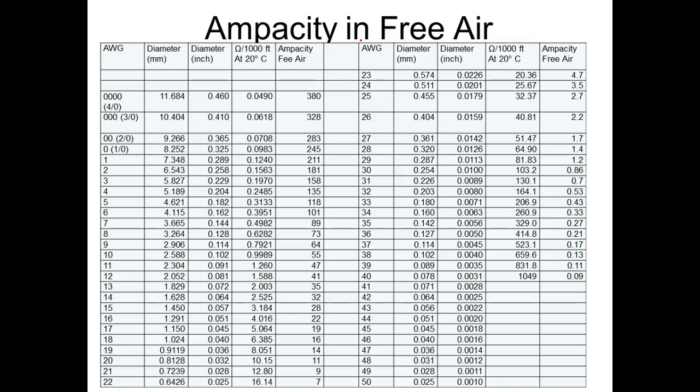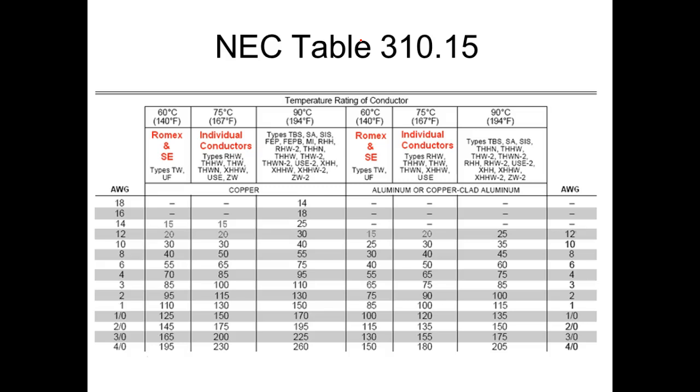Okay, so what does the National Electrical Code rate a 14 gauge wire? What do they rate a 12 gauge? Here's the NEC chart. They rate a 14 gauge wire, 14 gauge, they rate it what? 15. So they derate it so much. Why do they derate it so much? Why don't they rate it at 34? Because first of all, it's going to be insulated, right? You understand? Second, it's going to be run in Alabama, right? In the summertime.